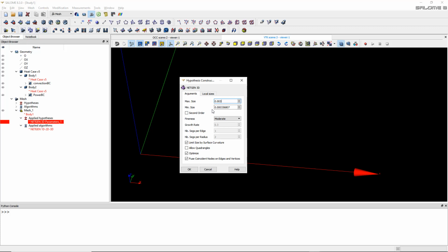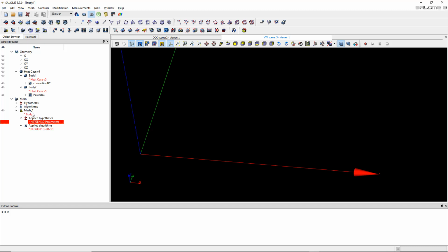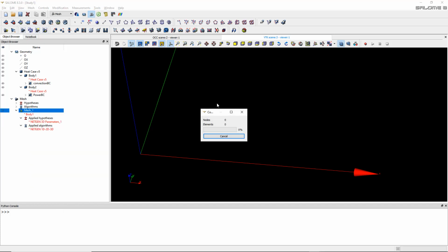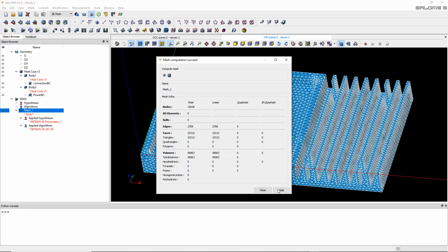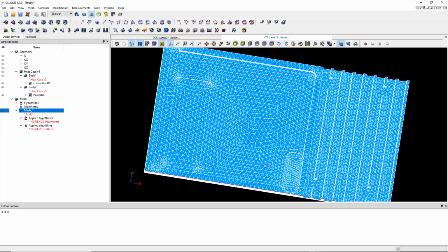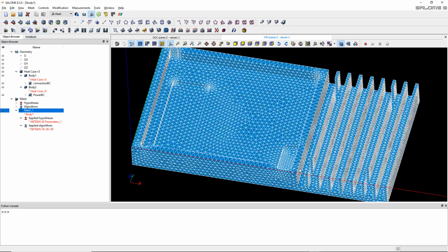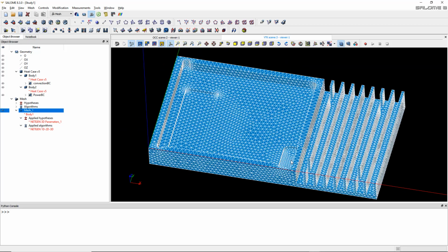Now for thermal analysis, I think Code Aster is actually working better with first order mesh. So in case you know about that, please leave a comment and let me know, because I'm not totally sure, but I think it's better to leave it as a first order. So I'll do this and let's remesh. Okay, and that's much better, I think. Could still decrease a bit, but well, let's use that and we'll see.